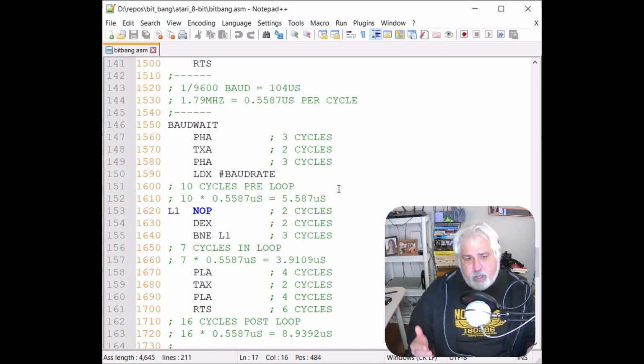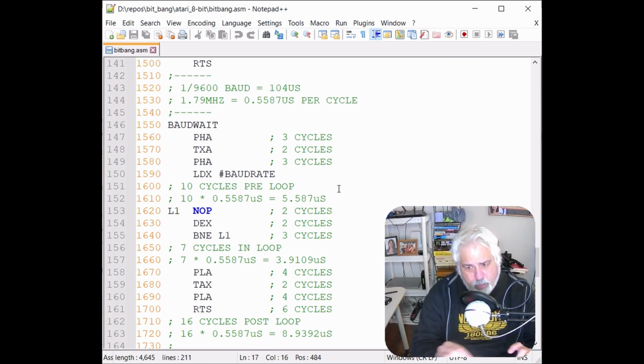You could use a profiler to take a look at how long your write bit routine is taking. So the code to actually write the bit, how long does that take? Then what do I really need to wait afterwards for the next bit? And you can probably get away with some type of delay-like function. If not, you can also look at things like interrupt-driven code to do the writes. You could write into a buffer and then have an interrupt fire based on a timer to pick up each bit or each byte, so you're not actually wasting time.